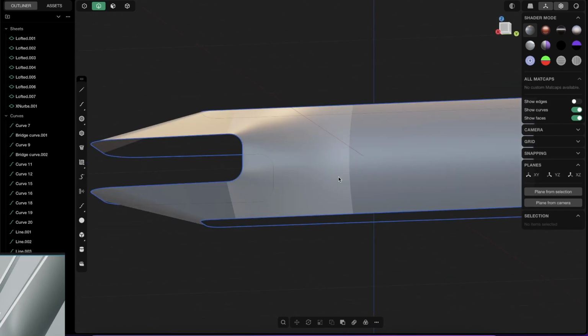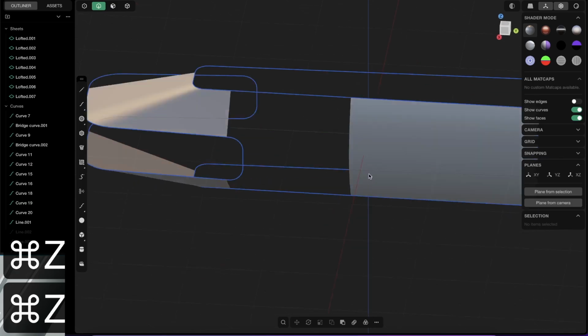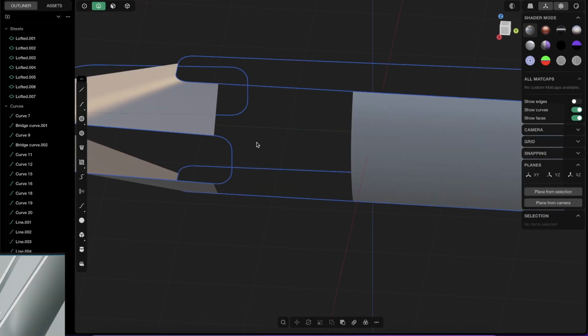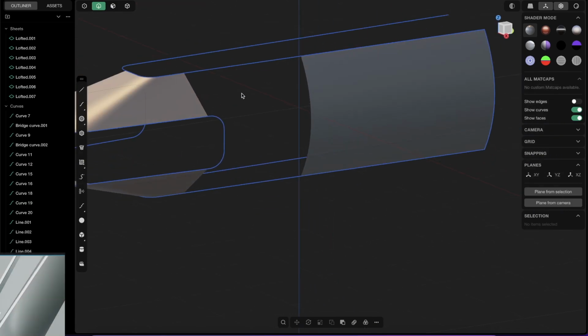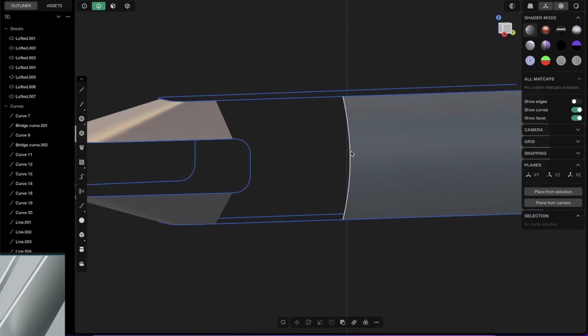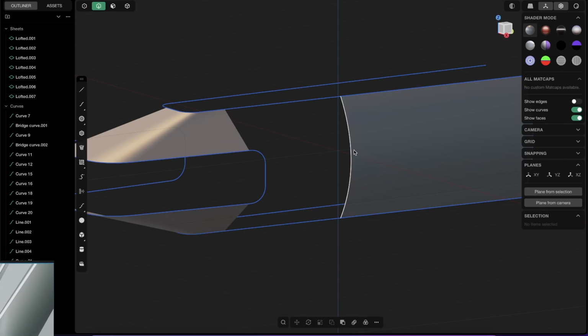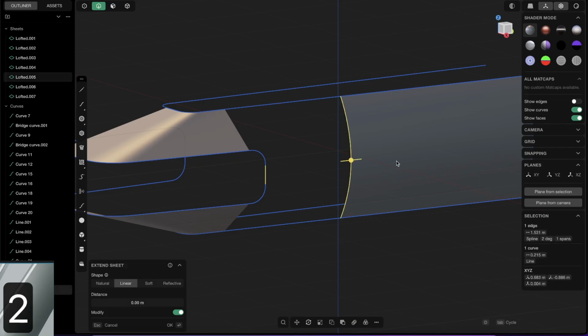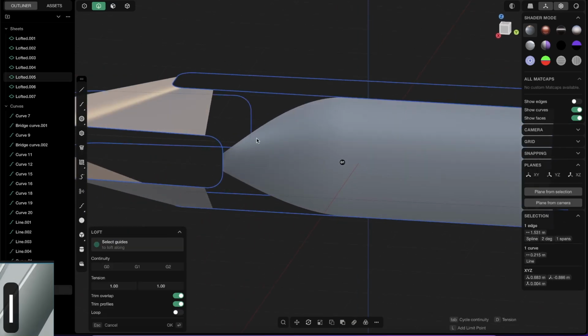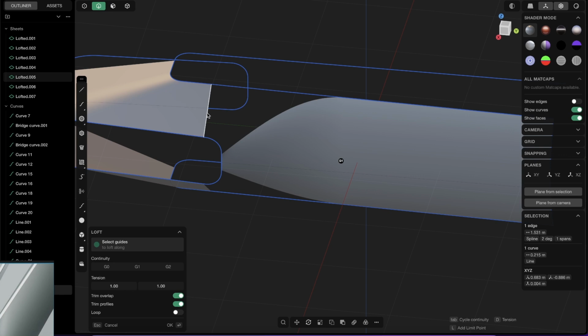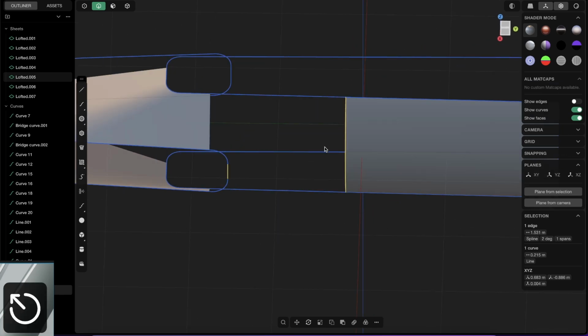It's really fun. But let me Control Z, delete that, because if you don't have xnurbs, it's fine as well, but it just needs much more manual work. But again, here just check and observe our hole, and here we have a long, straight line. So we also wanted to connect it somewhere here, but not in this way, because then we have this squeezing here, so we don't want that.